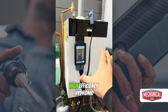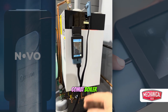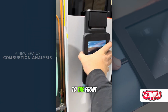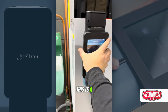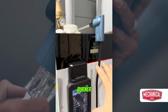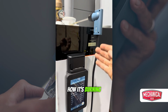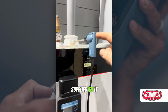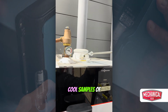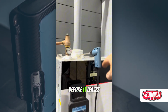And this is a high efficiency hydronic heating boiler. Okay, it's actually a combi boiler. What I'm going to do is focus on this thing kind of strapped to the front of it. What is this? This is a combustion analyzer. We're testing how the boiler is operating for its efficiency, how it's burning the fuel being supplied to it, by taking really cool samples of the flue gas out of the flue train before it leaves the building.